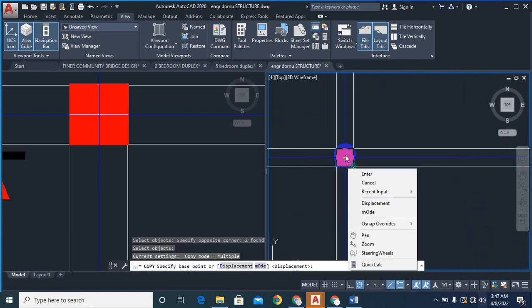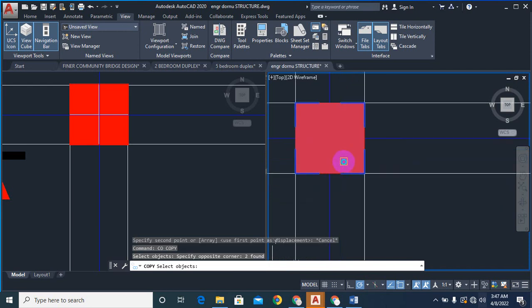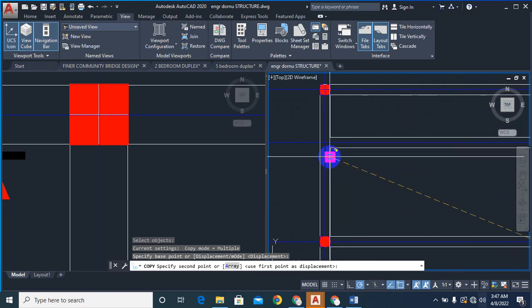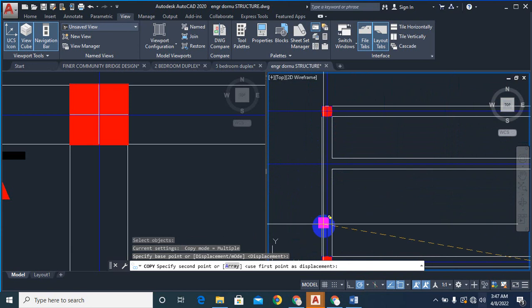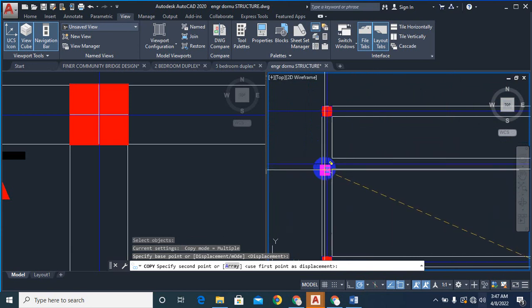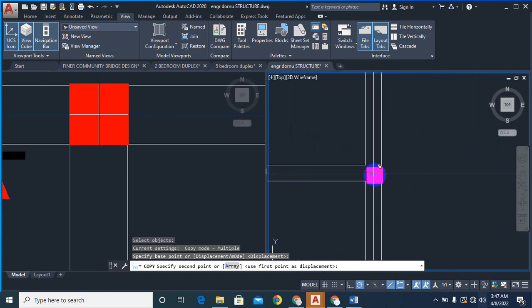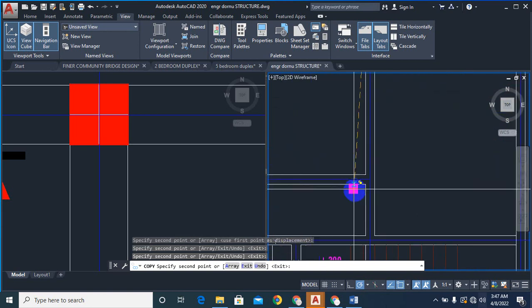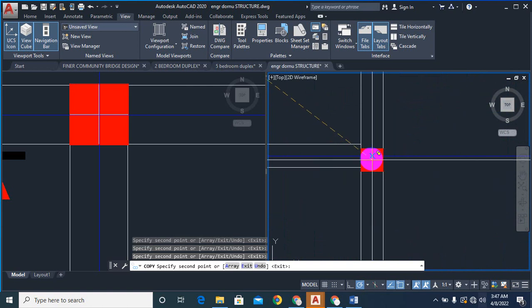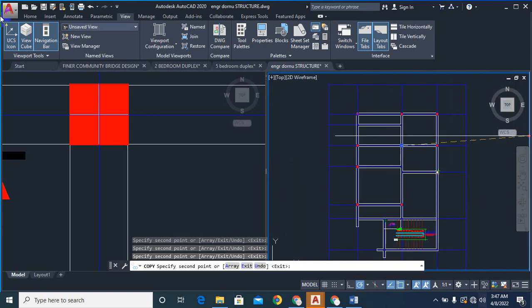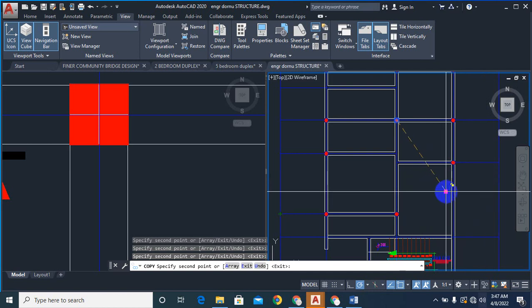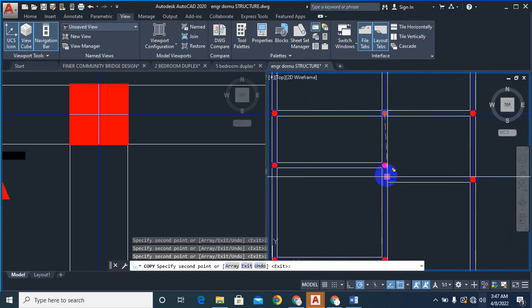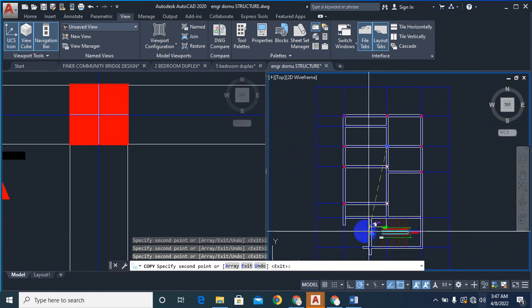To make that more economical, I can skip here. That means this beam is going to be acting on this beam as a point load. So this beam that comes this way is the primary beam. This beam that is acting on this is the secondary beam. I hope that English is not too strong. I believe you understand that. So this is a way of just making the design much more economical. Like if you can remember, I said your design has to be safe, and not just being safe, your design should be economical. But you can see here now, I can even as well leave this as a point load on this beam, but let me confirm the span.